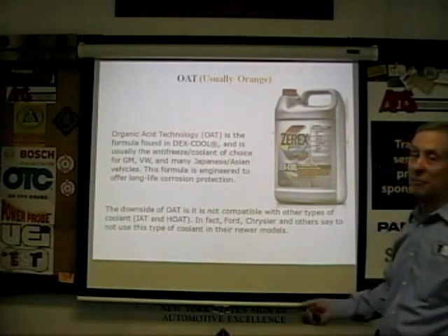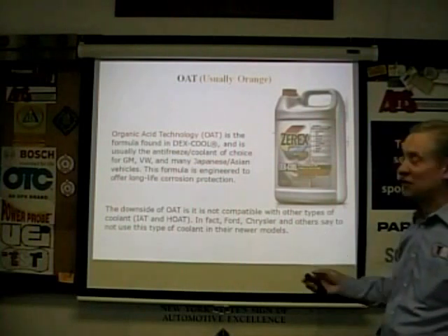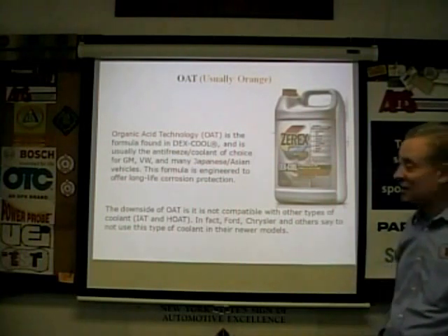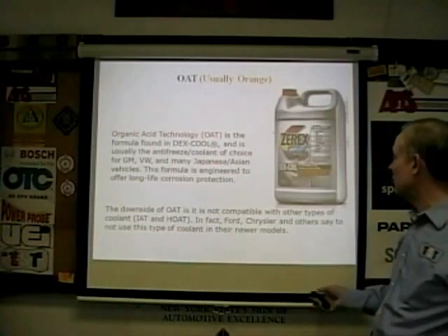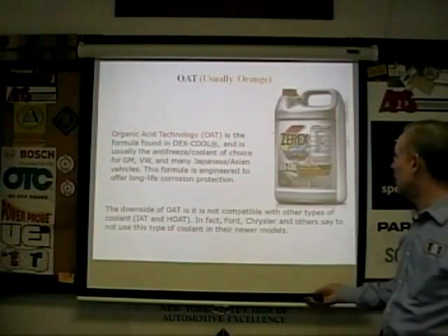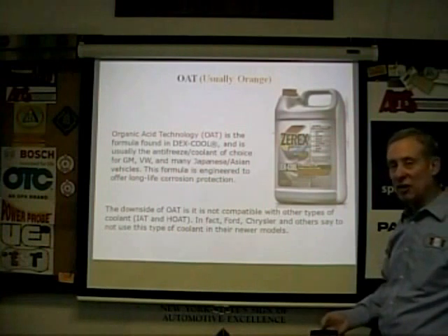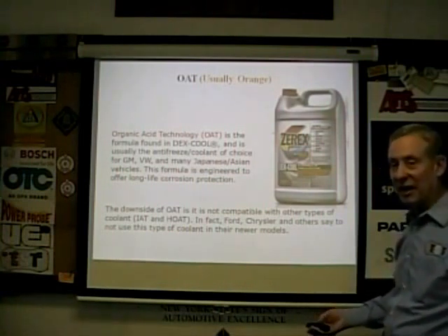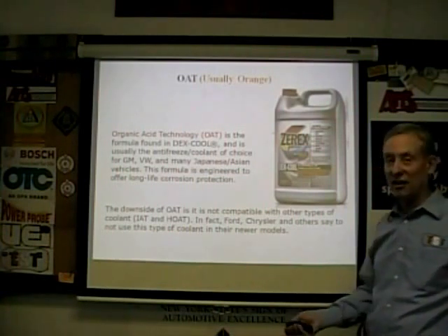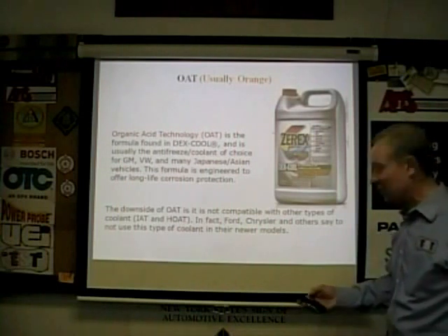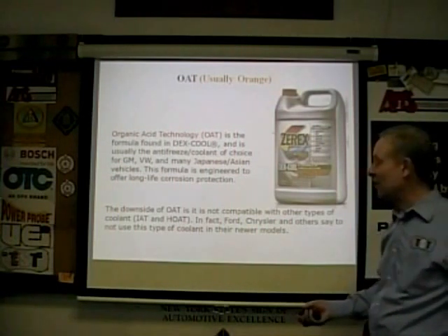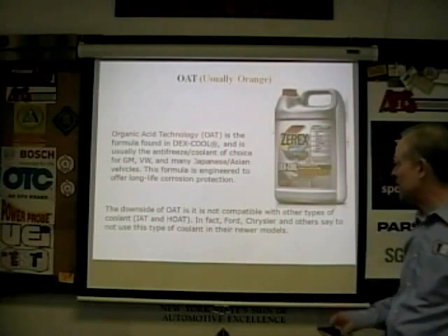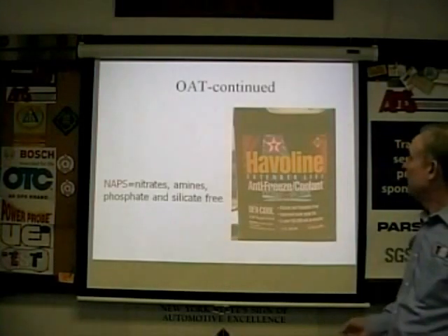Downside, it's not compatible with other types. That's why I said flush it. I'll say it again. If you don't know what's in the system, drain it all out, flush it all out with water, make sure it's clean, and then put in the right stuff. Otherwise, you can end up with things precipitating out of it. You can get the jello effect, the goo effect, different electrolysis effect, or pH issues where you have massive corrosion problems.